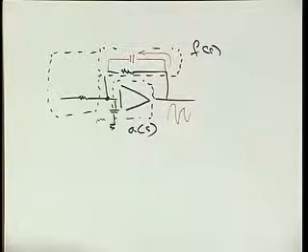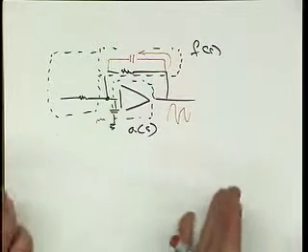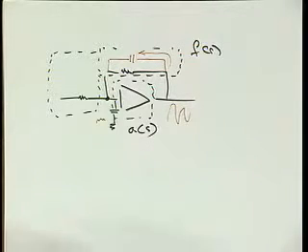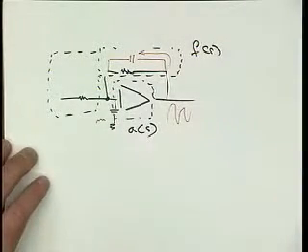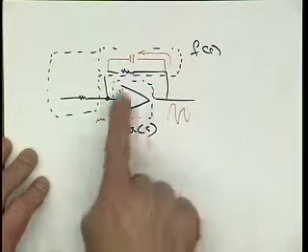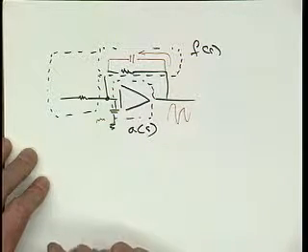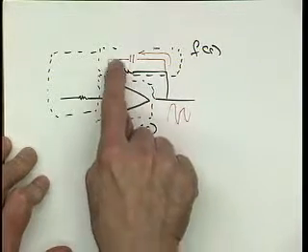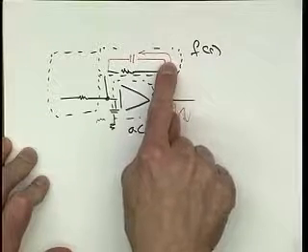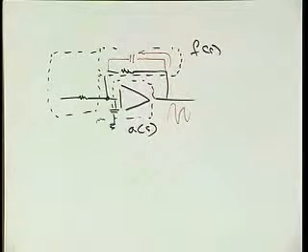And the feedback analysis schemes are not even used to analyze that circuit, right? So you can use the two-port thing, but be very careful. If you use transconductors, you really have to carefully account for the loading, and you have to include the feed-forward current through the capacitor also.